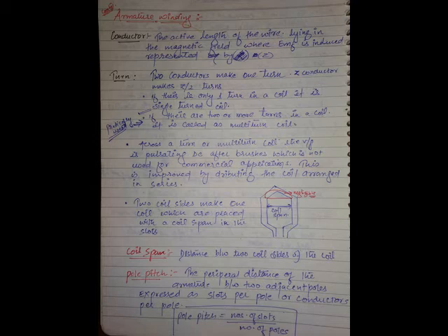Here you have to know clearly what are mechanical degrees and what are electrical degrees, and the relation between them. Now, if there are two poles in a machine, consider one complete mechanical rotation of 360 degrees mechanical. In this rotation, you will have a positive and a negative cycle.